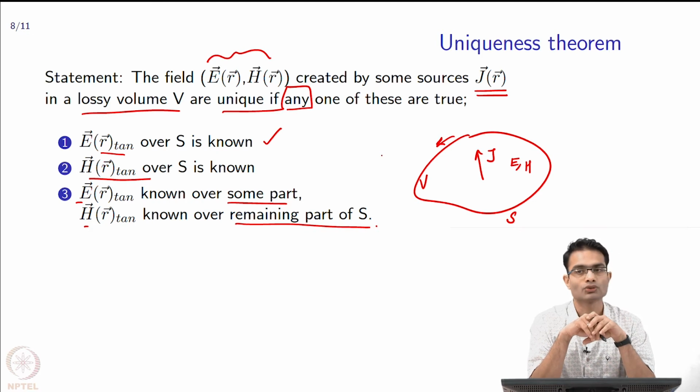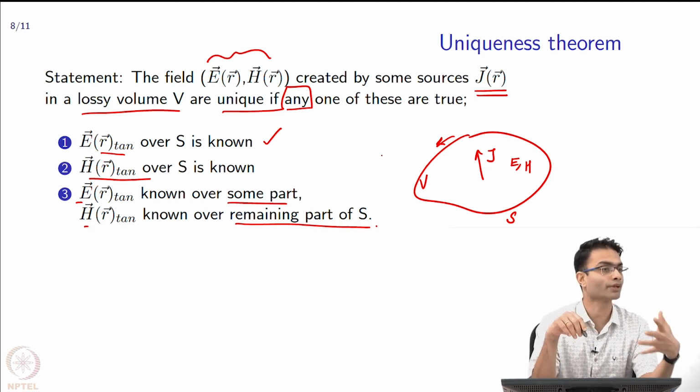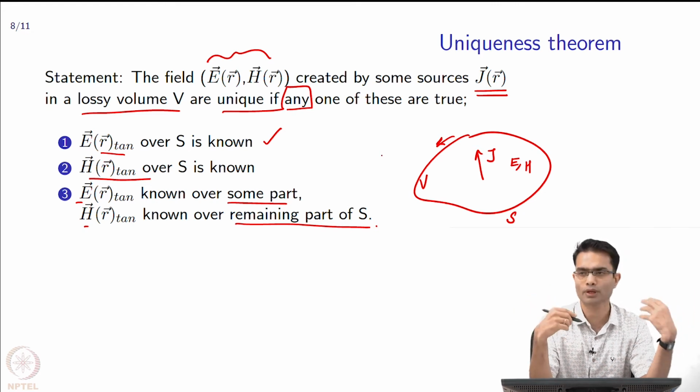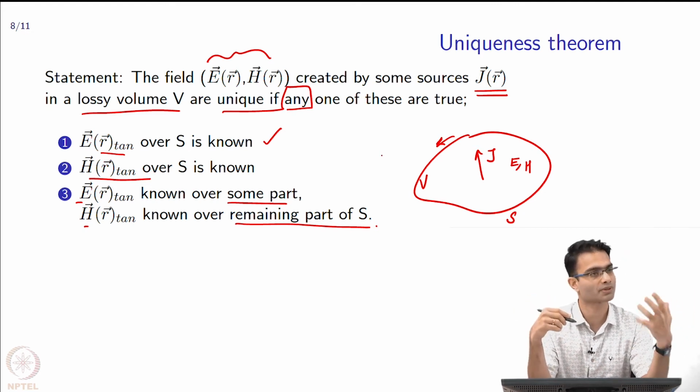So, this also tells you that if you were to approach a CEM problem, you need to specify the tangential E fields on the boundary. Once you do that, you are guaranteed that whatever procedure you use for solving these equations will give you a unique solution.